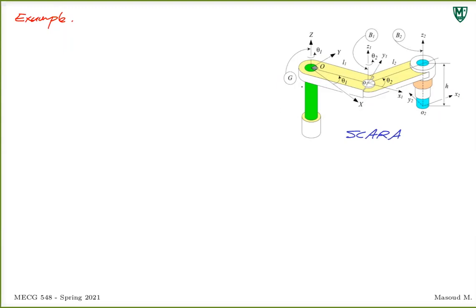In this case, let's look at the system itself. You have a revolute joint here, right? The green part, you can think about this axis Z. Or not the green part, let me be more accurate. This link right here can rotate around Z, and the rotation is represented by theta1. So we can have a rotation in this direction. It's a revolute joint. This joint right here, I'm going to make it so ugly at the end of this, is a revolute joint. The link right there can rotate around the green link, which is a fixed link.